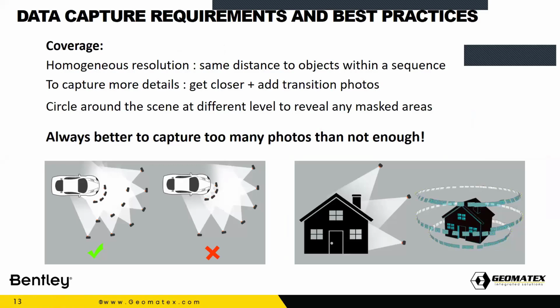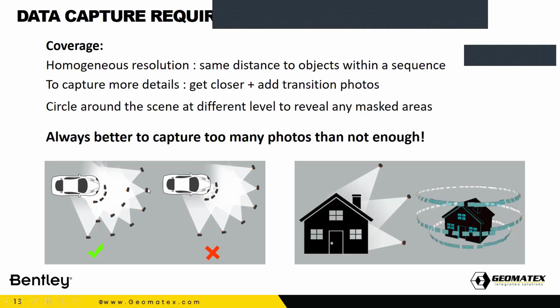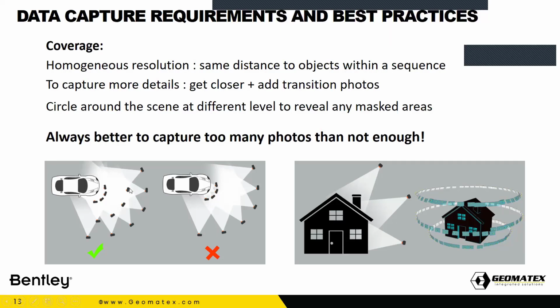Also, one of the most interesting points to be covered in this session is the consistency of the imaging. So if you are taking images from different angles or from different depth, which means different height or different distance from your perspective, try to make them consistent. And if you are taking too close images like this and too far images, please make sure that you do another round which enables the software to connect between this data set and this data set.